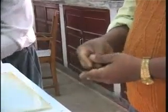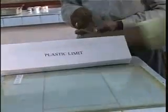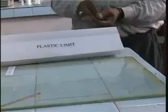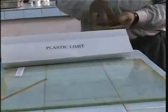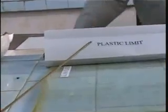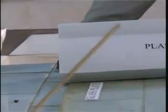So here what we do, we take a sample of soil and we try to roll a thread which has got a diameter of 3 millimeter exactly. Means if we can roll a thread with the sample of soil which has got 3 millimeter diameter, then we say that the soil is at plastic limit.